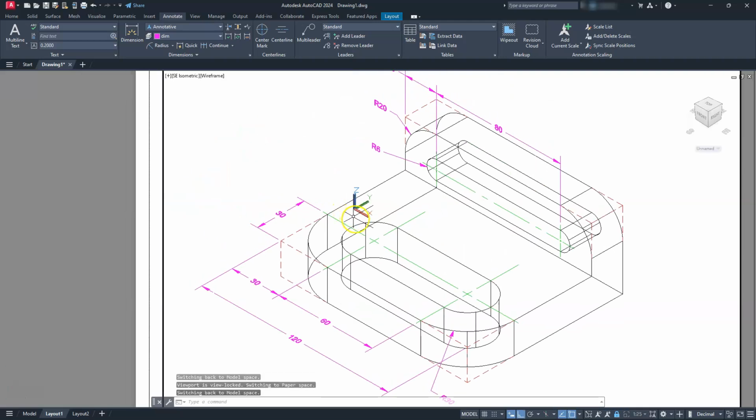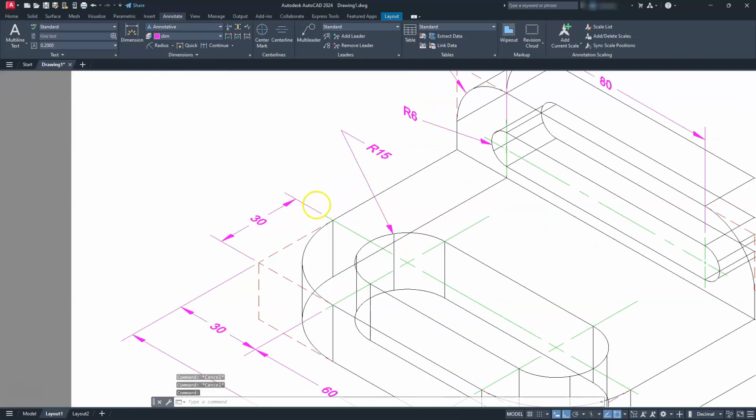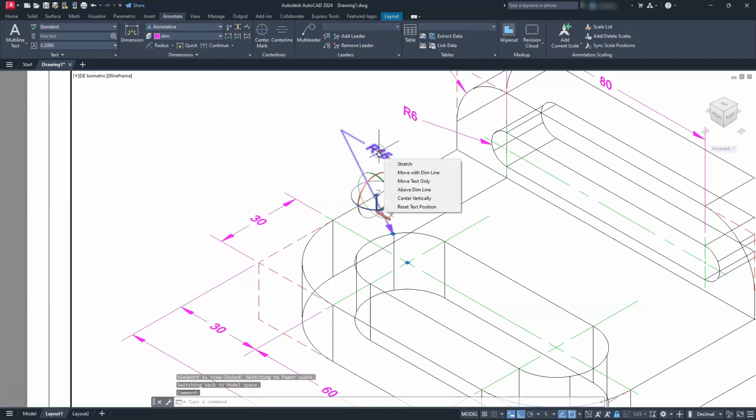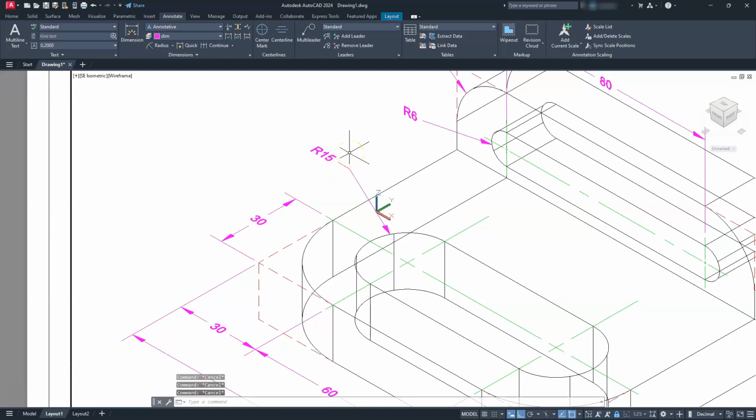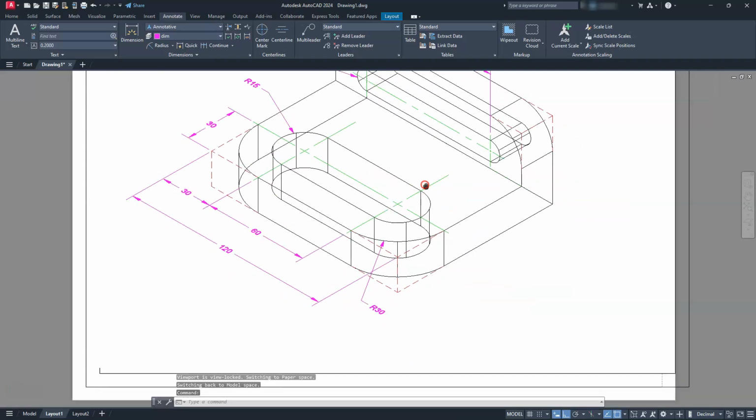All right, let me go ahead and place my dimension here as well. I have a radial dimension located somewhere here. Now this one might be a little jacked up, and if it is, that's okay. Go ahead and place the dimension, and then when you try to relocate it again by selecting that grip, it will spin around to the right orientation.